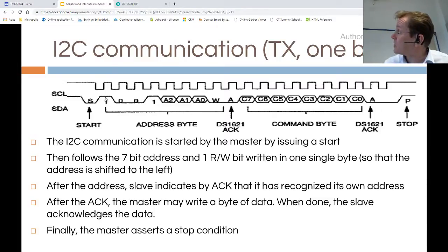So that's the protocol. And I always forget this acknowledgement bit. When you are writing an address and there is a device, then this acknowledgement bit is actually given by the device. When you are reading data, then basically the master should put the acknowledgement there. Okay, data received.